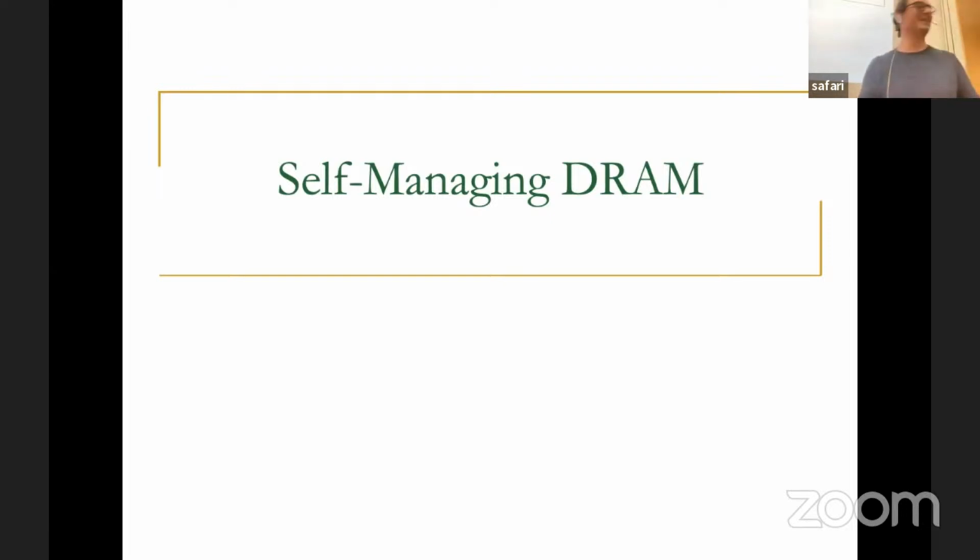Rahul can help. Okay. So I want to conclude the memory controller lectures with a work that rethinks the interface a little bit. Not hugely, but I think this is an improvement over the existing interfaces. Essentially, if you look at the interface that I described, the memory controller dictates everything, right? A DRAM chip has no freedom. It's not autonomous. It's really basically obeying what the memory controller says. The DRAM chip itself cannot power down anything. The DRAM chip itself cannot refresh anything. It basically obeys what the memory controller does.